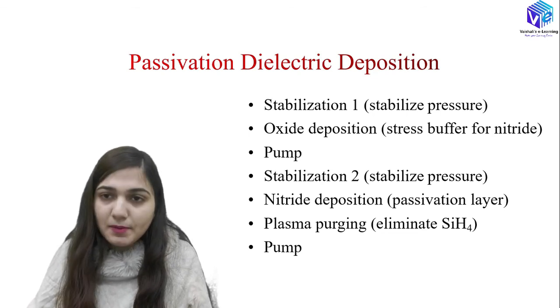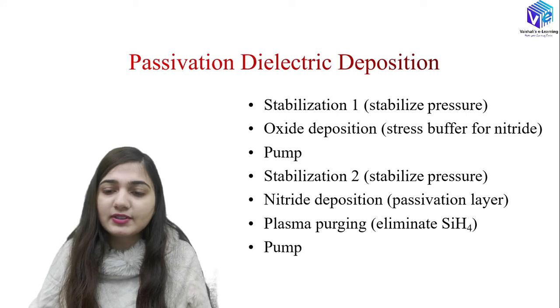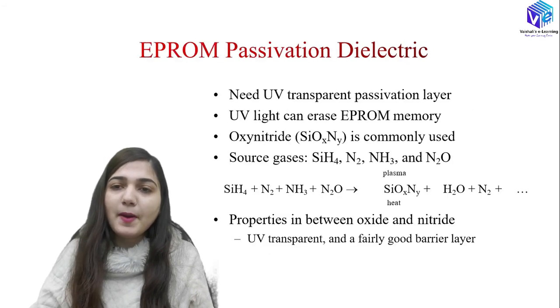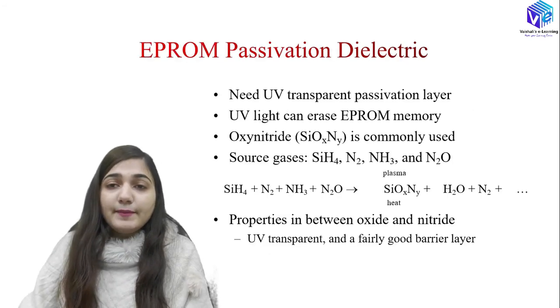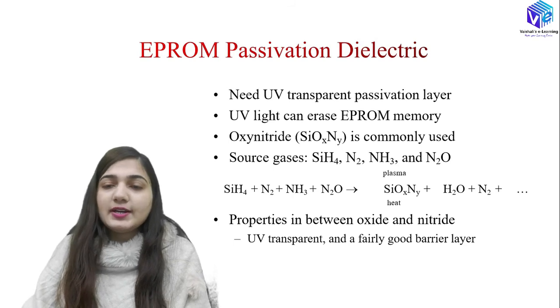This is our actual passivation layer deposition, and after that we are going to do the plasma purging to eliminate the SiH4, and again I am going to do the pumping. So now coming to the EPROM passivation dielectric.